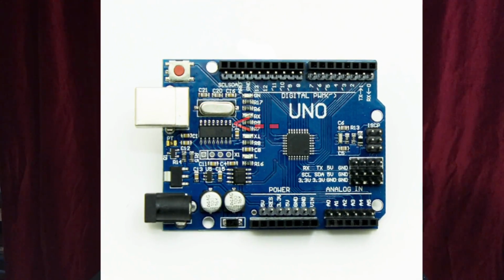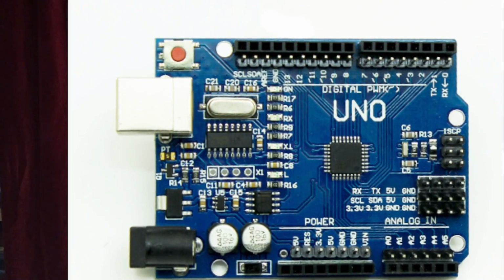So it's taking the data from the virtual COM port on your computer, sending that to the 16U chip, which converts that to serial and then sends that to your Atmel chip. Or with the clones, it'll be a CH340G, that's usually what they use, which are slower and they misbehave and you have to use custom drivers for them, but whatever.